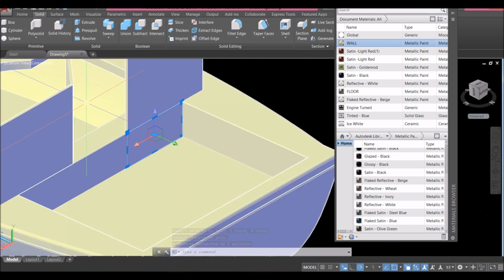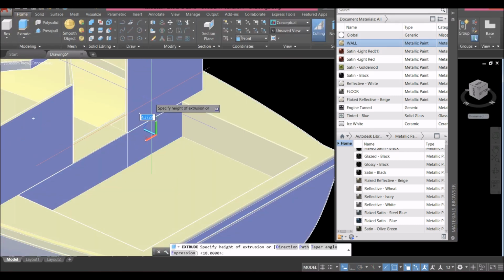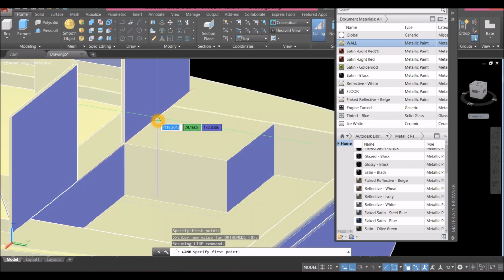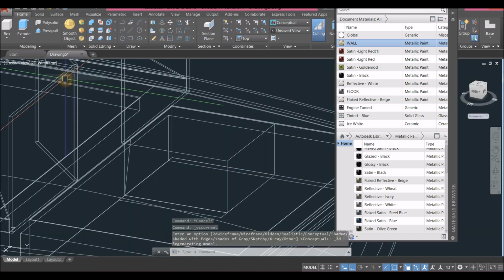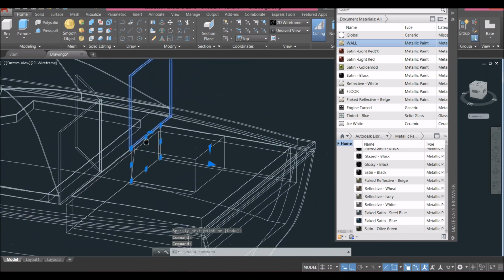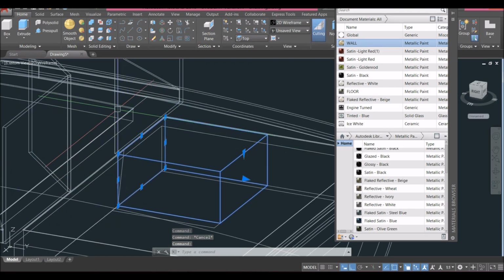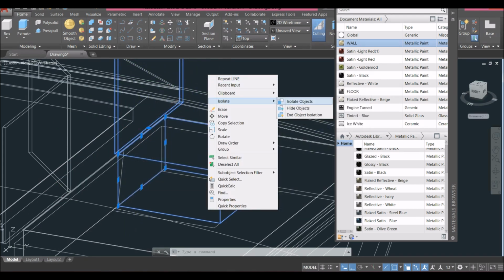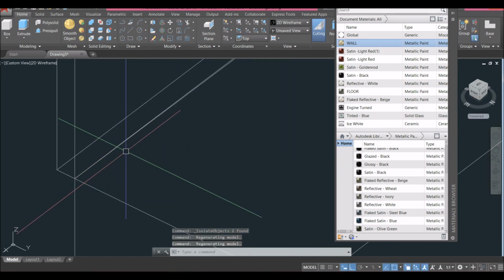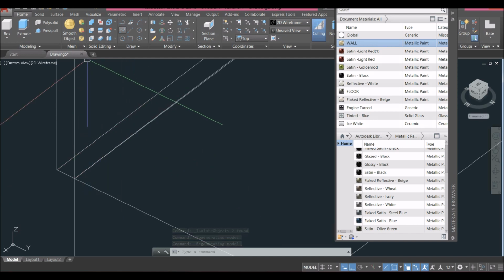There you go. And I'm gonna extrude this one. So go to home, extrude forward for about 16 units. I'm gonna highlight this one here and this one, so I would know which side to put that rectangle here. Okay, so isolate. All right, and you can hide this one now, or just use polyline.